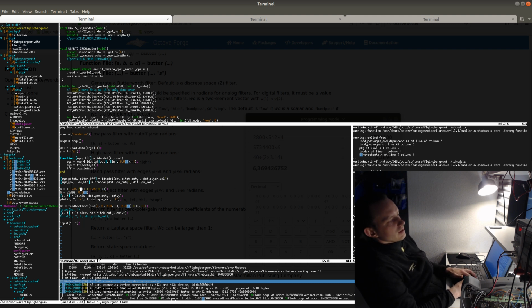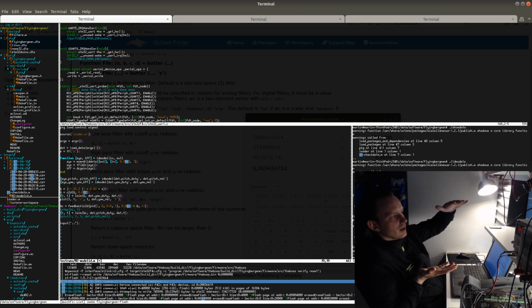In this transfer function, the first parameter is the DC gain. This is a first order transfer function, and this parameter is the time constant. So this is how many seconds it takes, if you do a step response, for the output signal to reach 63% of the input signal. The 63% is calculated based on the natural logarithm. There is a formula for it, I don't remember it in my head, but the 63% is the level which coincides with the time constant of the system.